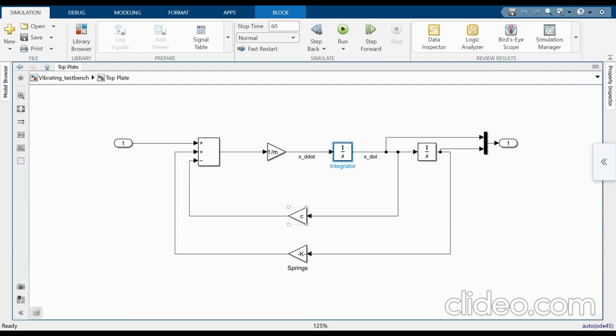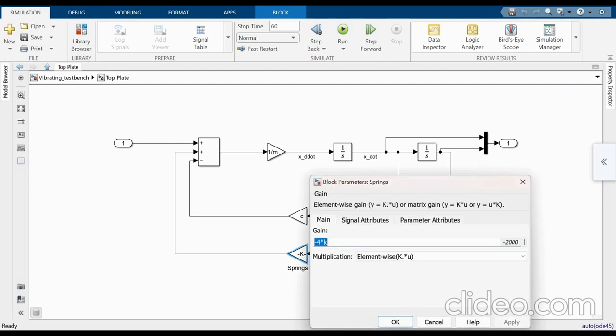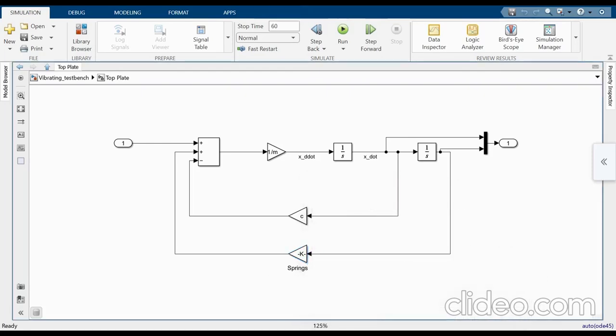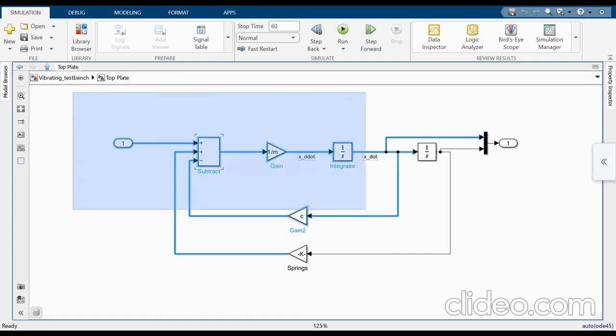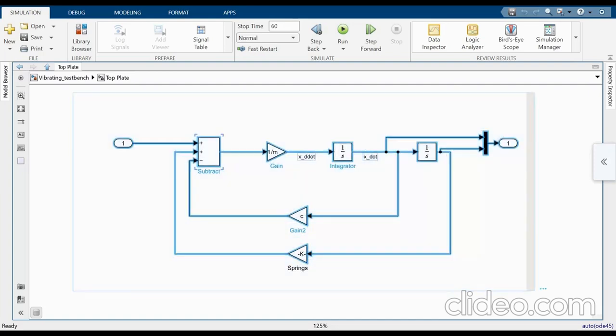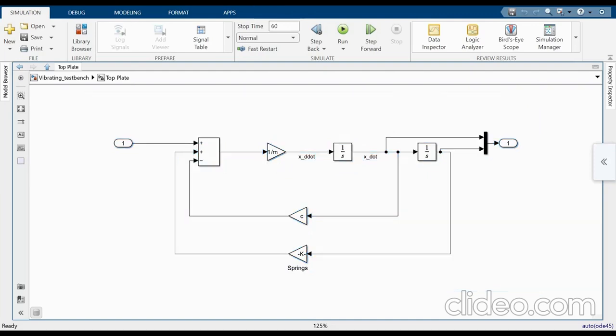Similarly, a block was used. The signal from this asymmetrical mass is logged to the goto block, and from the goto block to the from block and to the scope block for readability. The values that the block depends on are the bearing mass and the offsetting radius, which causes vibration.